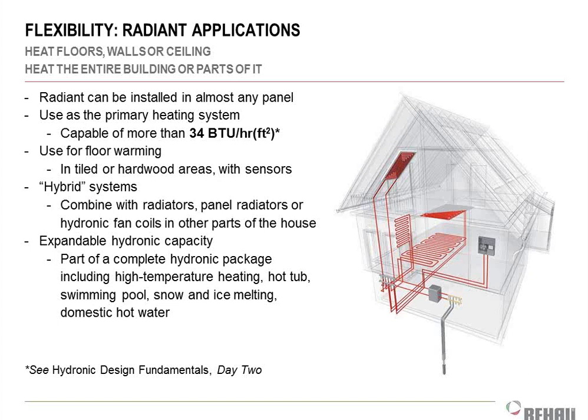You might hear that referred to sometimes as a staple-up system or an underfloor system. We call it staple up because traditionally you'd go underneath the basement floor, you'd lay all this tubing on the ceiling, and you'd literally staple it up to the ceiling. Now, obviously, you're not stapling through the pipe. You're stapling large staples around the pipe.